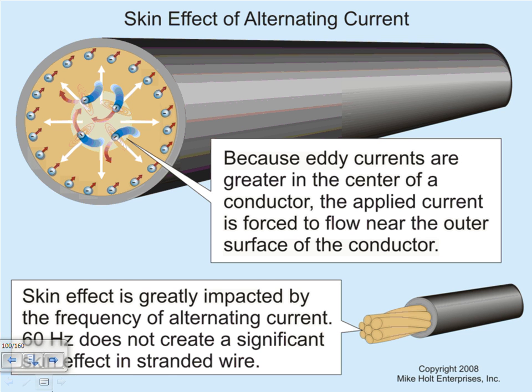So, for example, the skin effect, the stranded wires, look at that one. The current tends to flow at the surface of a conductor instead of the core of a conductor. Believe it or not, the power companies, you know what they do with these power lines? The core of the power line is a steel wire, and the surrounding is an aluminum wire.